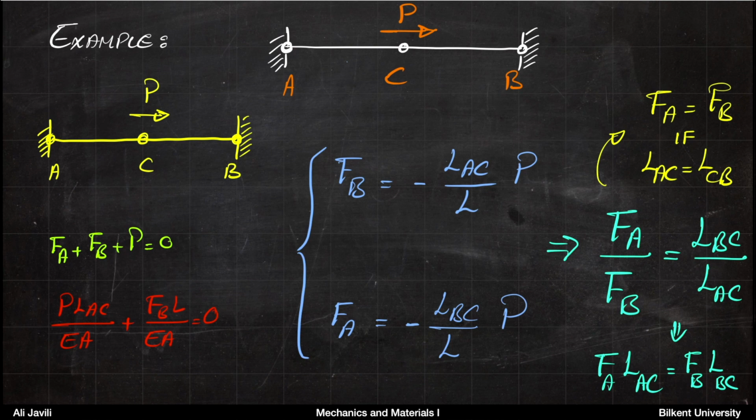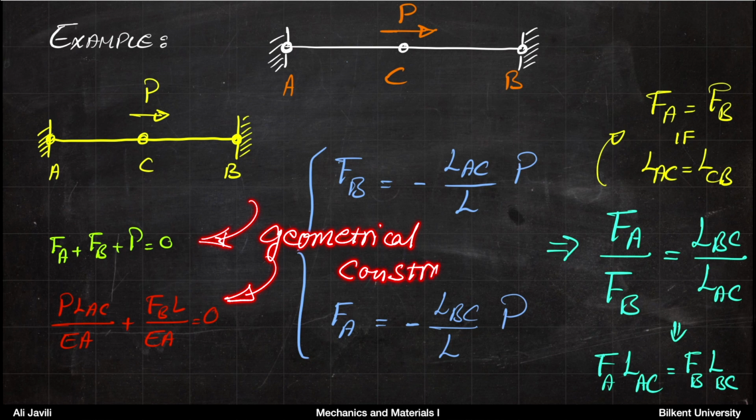So whenever you get a statically indeterminate system, you should always start with your free body diagram and the common equations of statics, like equilibrium equations that you have. And then you always need an additional constraint. In this case, it's a geometrical constraint, or it came from a geometrical constraint. At this point, you just see it as forces, so you don't see the deltas anymore.